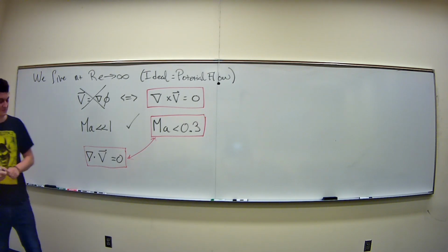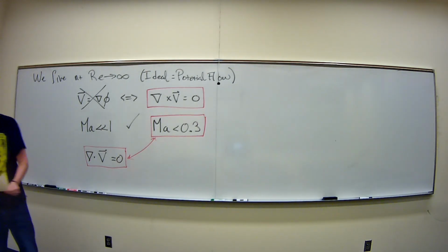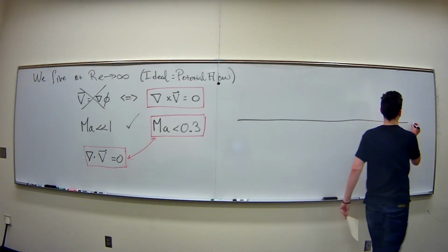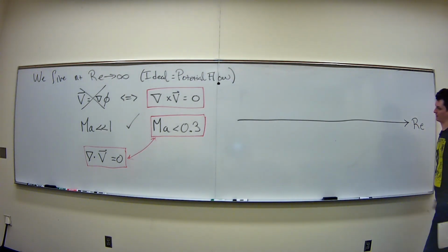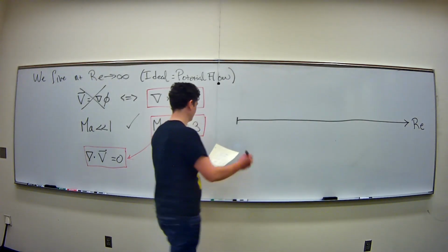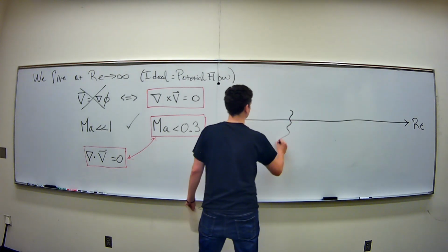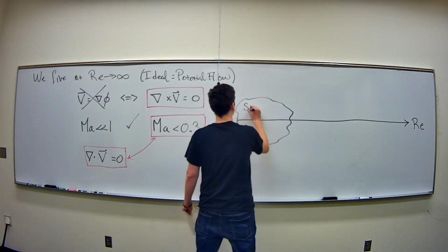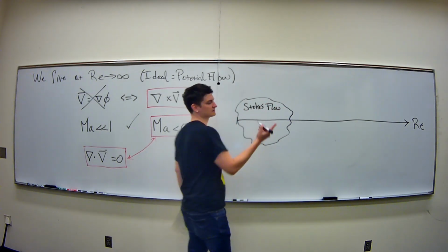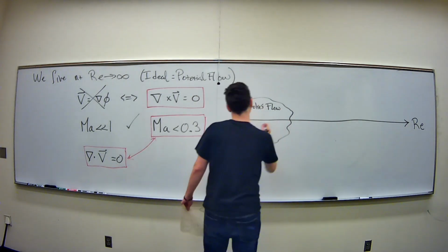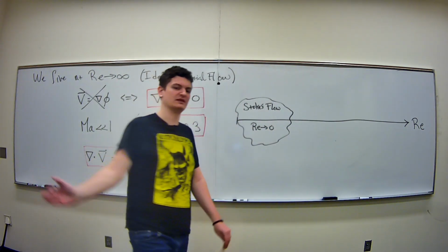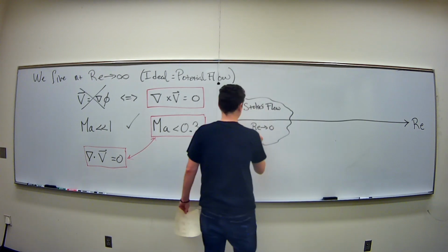Okay, so maybe to summarize where turbulence is, I have this nice little thing going on, right? You have to think of things at all stages of these equations. I have some Reynolds number scale for any type of flow scenario. So there is this Stokes flow world, right? And in the Stokes flow, where we went over a whole last lecture, you're really going to zero. You have linear equations, and all the nonlinearity dies out. So this is a linear theory,